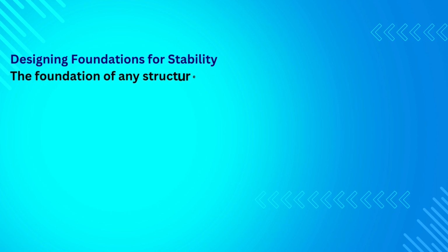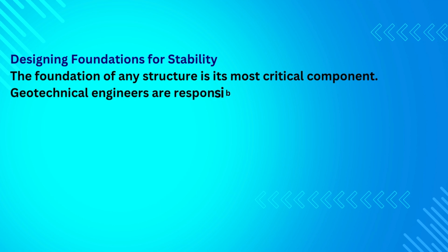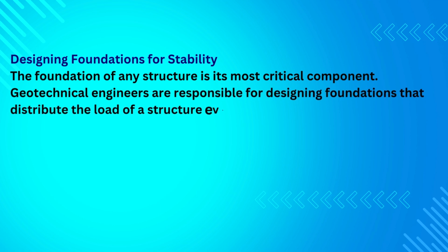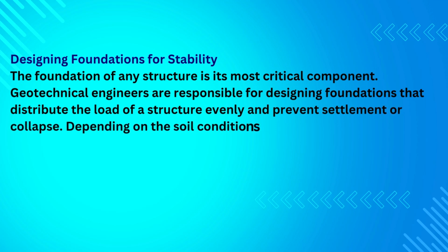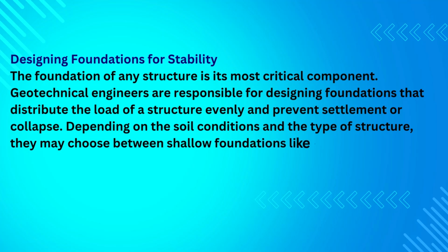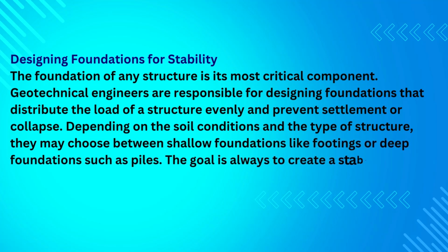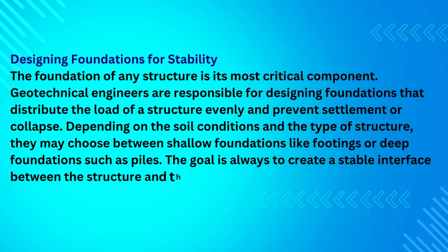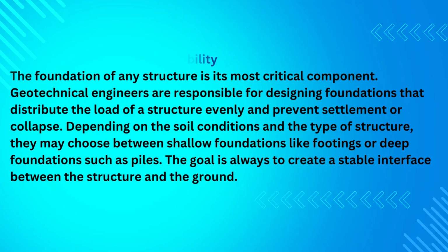Designing foundations for stability. The foundation of any structure is its most critical component. Geotechnical engineers are responsible for designing foundations that distribute the load of a structure evenly and prevent settlement or collapse. Depending on the soil conditions and the type of structure, they may choose between shallow foundations like footings or deep foundations such as piles. The goal is always to create a stable interface between the structure and the ground.